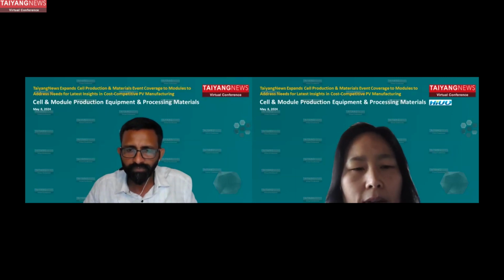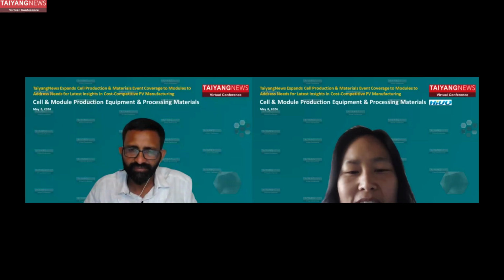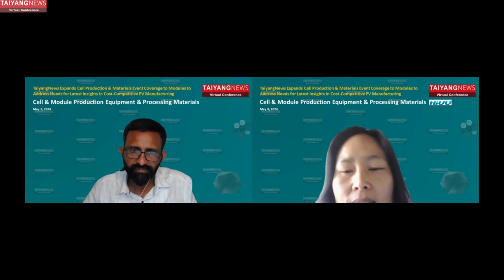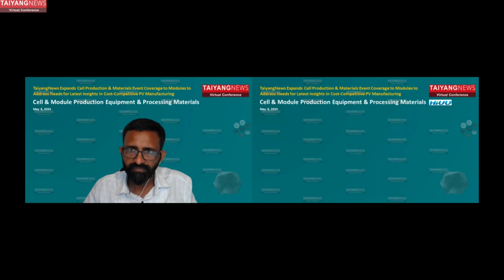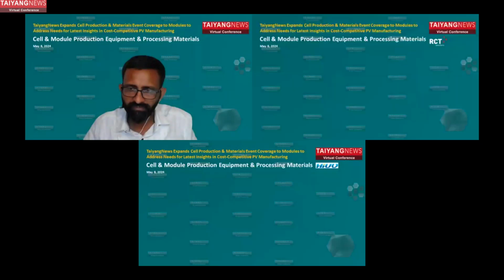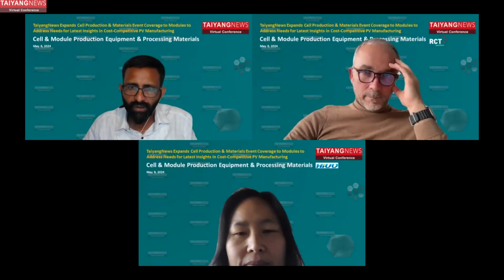Okay, yes, TOPCon is very hot recently. The market share is increasing day by day. In China, module manufacturers are focusing on cost reduction and efficiency enhancement. Some have already started to use double EVA encapsulation schemes, which have been successfully tested and are currently in massive production with some of the clients. In that way, they can bring the cost down.